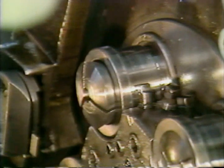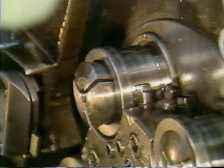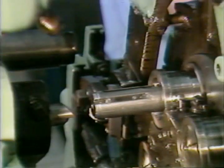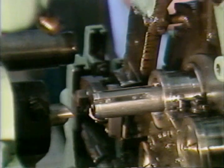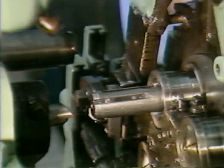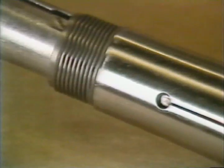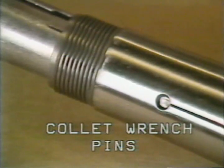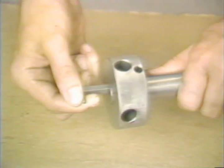Be sure to clean the spindle and collet with a brush and an approved solvent. Replace the collet if it is worn or broken. To insert the new collet, place the collet wrench through the back of the spindle. Align the collet wrench pins with the holes in the collet. You will need to push the bar on the end of the wrench to engage the pins.